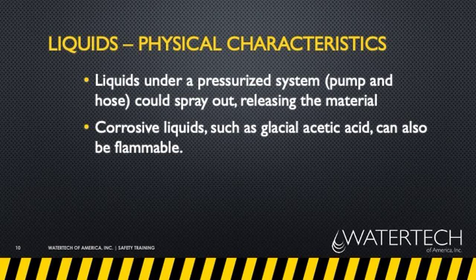One of the main hazards we deal with is pumping chemicals. We had an incident where we were transferring chemical, and when the pump came on there was a little pinhole in the plastic tubing, and chlorine came out and squirted our rep in the eye. We got him to the safety shower right away. And eventually, he went to the hospital as a precautionary measure. Everything was okay. But again, we run into these situations where you don't think something will happen, and you're not wearing your safety glasses, and then something goes wrong. Make sure to always wear the proper PPE. And when you're working on pumps, de-energize them so that you don't have to worry about this type of situation.